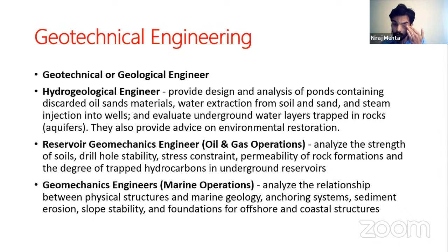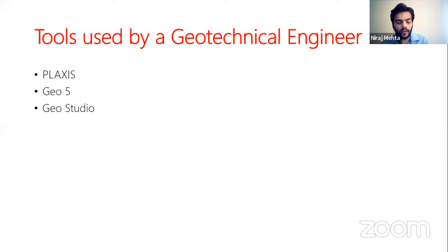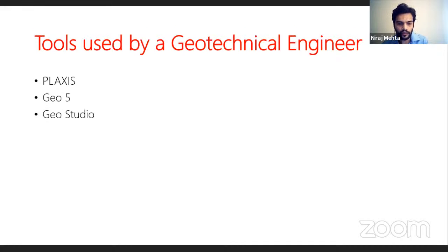When we talk about a geotechnical engineer, there are not many tools available, because a geotechnical engineer has to do the boring, collect the samples, and then run some tests. As we have learned in our bachelor's, for geotechnical experiments we have done the direct shear test, triaxial test, and vane shear test. All these different tests are there to understand the shear strength parameters, water capabilities, and soil structure behavior. All this is basically done in laboratories after collecting the samples.